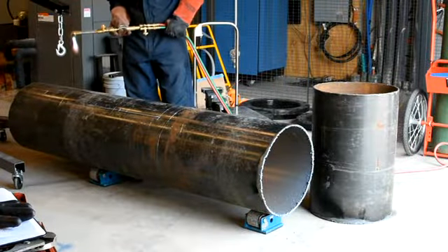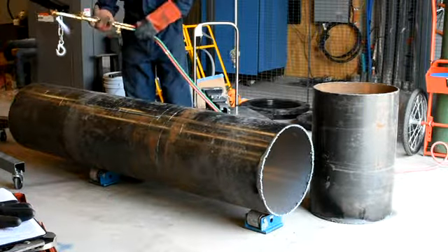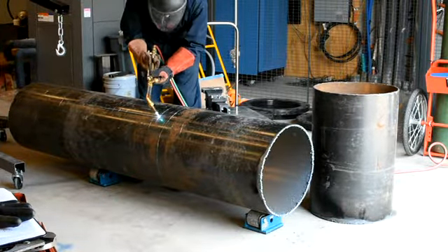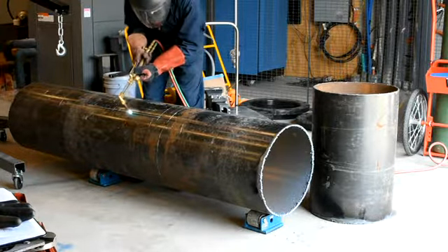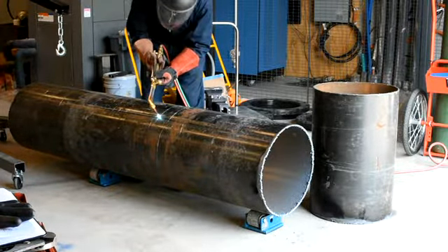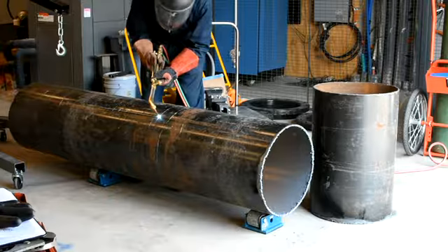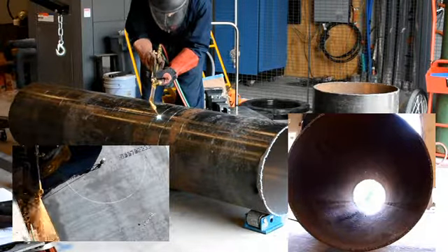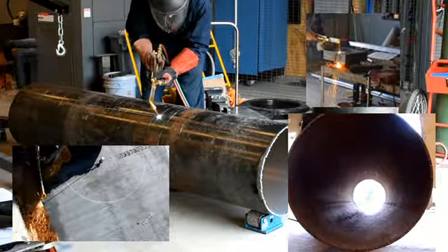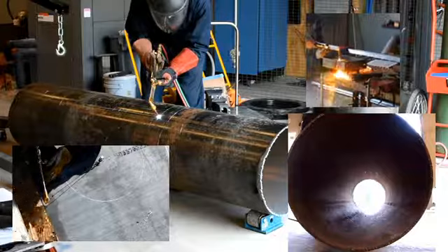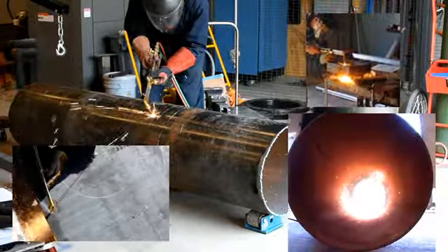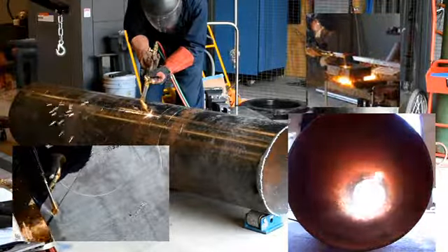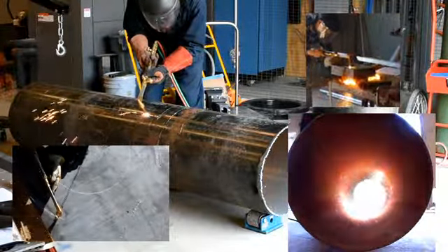Now let's see the cutting torch in action. In this case we're going to cut a mild steel pipe with a wall thickness of about 1/4 of an inch or 6 millimeters. So initially we preheat an area of the steel until it goes white hot with the torch. Then we depress the lever, which increases the flow of oxygen through the center of the tip on the torch. This oxygen reacts with the hot steel, oxidizing the iron, forming iron oxide, and in the process that jet of oxygen cuts through the steel.